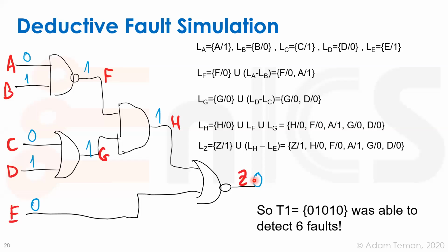Given the limitations that you can't really propagate exactly to the cause because of all the compression and all the deductive stuff, you can still get close to the area where the failure is caused. And I think there are tools that will tell you, if you give them the pattern that fails and tell them where it fails, what the suspected gates are.